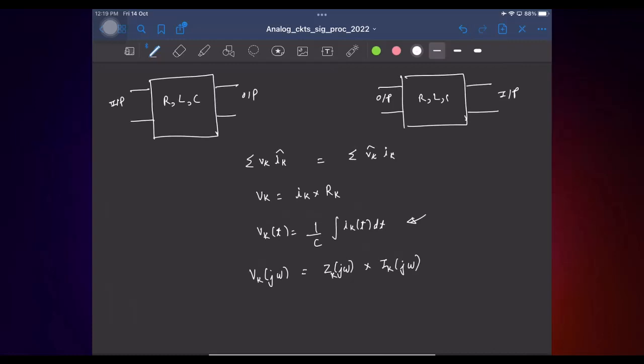Because this capacitor I assumed it to be constant. Please recollect, only for an LTI network can I write it like this. For an LPTV network we can only write in terms of the matrices. As he mentioned, here is where I assume that it is an LTI capacitor, and that is why I can write the relation like this. If the capacitor is varying with time, this relation is not complete, because Q of t is now C of t times V of t. So you integrate it, and you will have something.